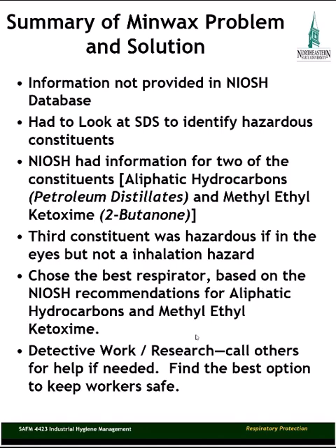And one other thing I'll say about Minwax or polyurethane or a lot of coatings, it's very difficult to use most types of ventilation when you're spraying or brushing or wiping on polyurethane, because you get that air moving, it picks up the dust and all of these fine particles.